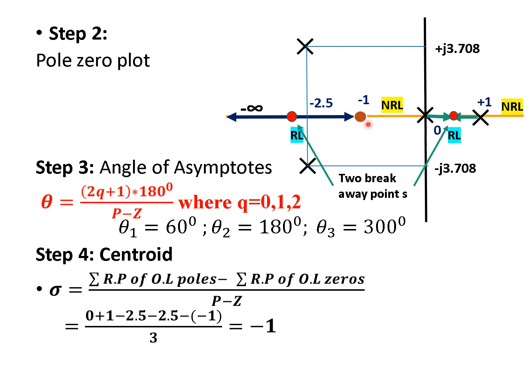Now let us see where the root locus exists and where it does not. If I keep the cursor at this point, to the right side of the cursor there are no poles and no zeros. That means it is a no root locus zone. Now if I keep the cursor at this point, to the right of the cursor there is one pole, which is an odd number, so the root locus exists from plus 1 to 0. Now if I keep the cursor at this point, to the right of this there are two poles, which is an even number, so there is no root locus from 0 to minus 1. Again, if I keep the cursor at this point, there are two poles and one zero.